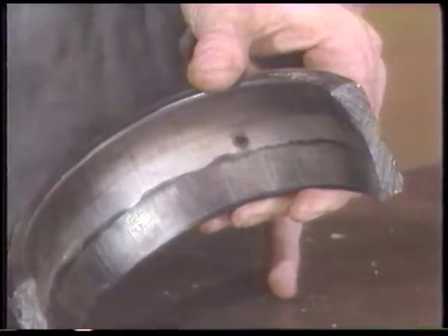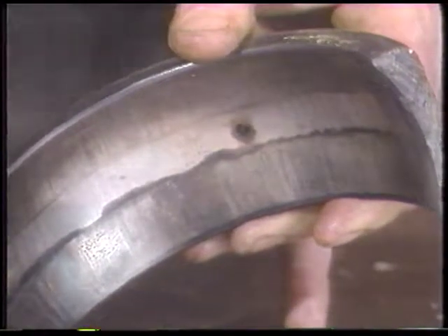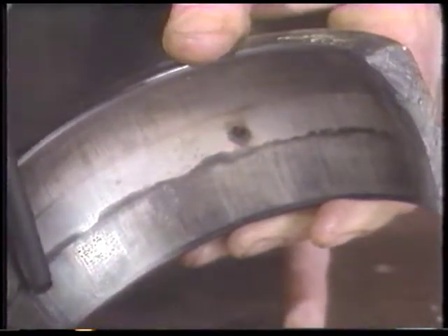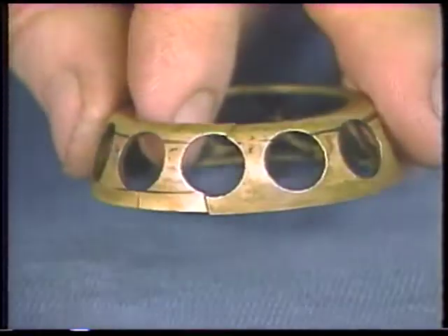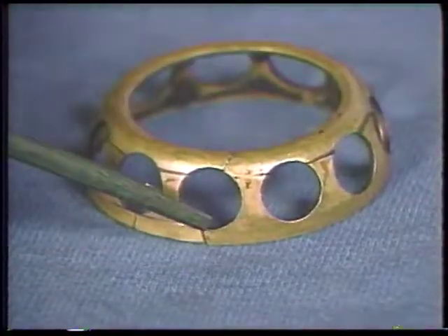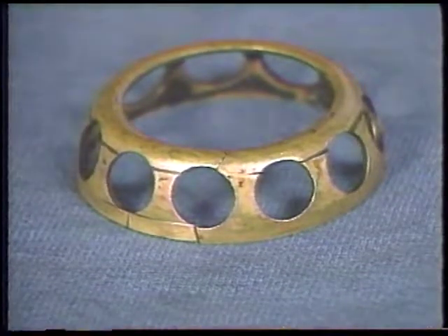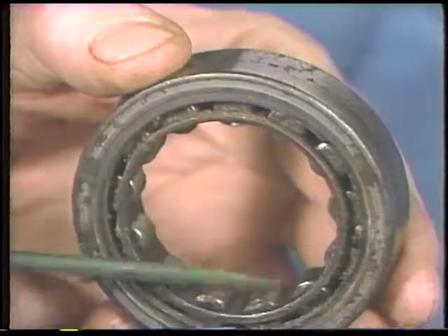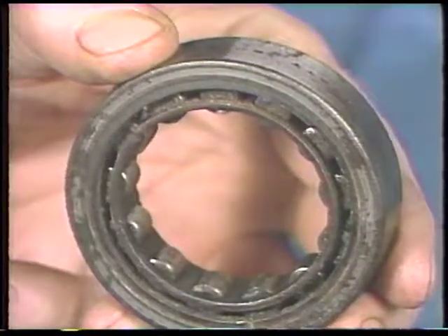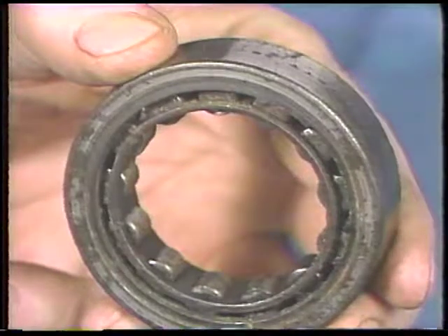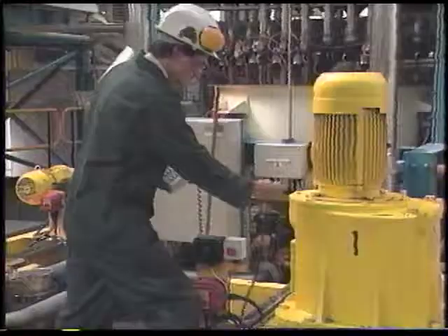A high tone or whine often means the bearing has been Brinelled. That is, the rolling elements have permanently dented the races. Random or intermittent clicks probably indicate a problem with the cage or retainer, damaged rolling elements, or dirt in the races. A crunching, grinding, or growling sound can also indicate dirt. Or it may indicate seriously worn rolling elements or races.